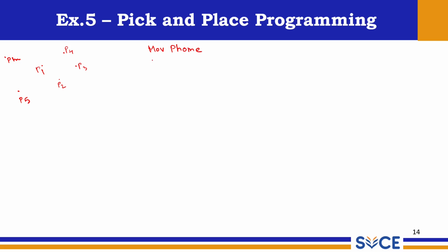The moment you do that, we are supposed to define the palette. How is that palette defined? PLT1, palette 1, comma, P1, comma, P2, comma, P3, comma, P4. Okay, I'll finish it, then I will explain. 4, comma, 3, comma, 1. So this is the statement we use. This particular statement governs the palette definition. We are defining the palette, DEF palette PLT1. This palette number is 1. P1, P2, P3, P4. These are the 4 boundaries of the palette.